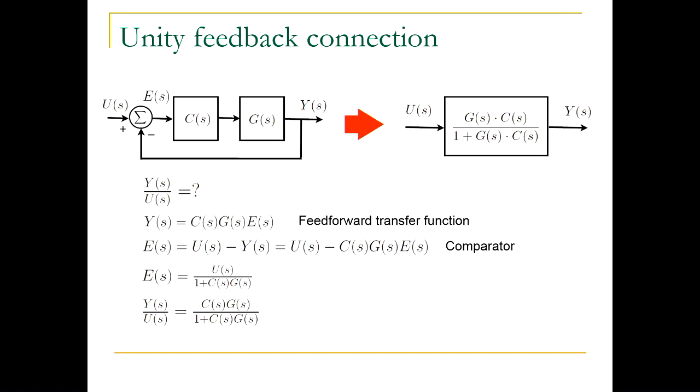If I go from E all the way to this signal here, it's still the same in this case. So on top, you need to write CG, whatever is in the feed-forward part. What you write here is basically the transfer function of the whole loop, right? In this case, these two things turn out to be the same because there was nothing in the feedback loop.